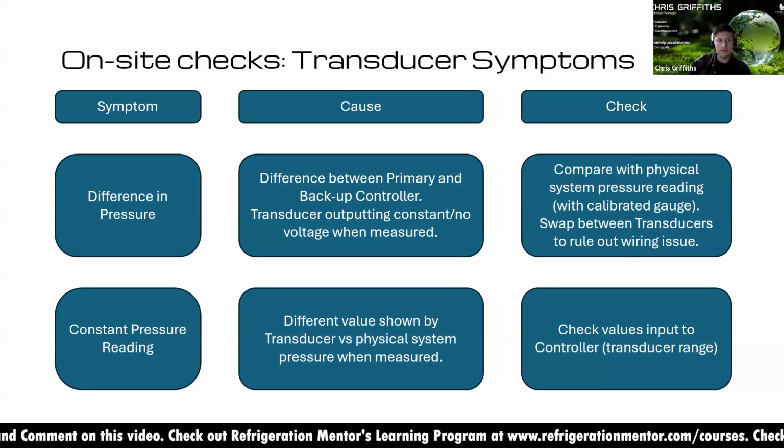Yeah. One of the issues I've found in the past is that work's been done on an island, and the transducer's been left valved shut. And afterwards, all those controllers are linked to this, but that pressure is not changing because it's trapped in that short section of pipework, and it results in incorrect control and liquid flowing straight back to the compressors. And thankfully, not quite a large enough island to really damage the system, but it needed investigation.